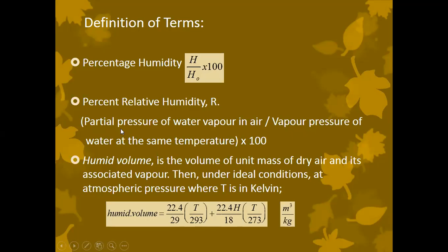These two are very different. Partial pressure is just the pressure caused by one component in a given mixture, in this case the mixture of water vapor and air. But vapor pressure is the pressure that the vapor of a substance is exerting at the particular temperature indicated. And this vapor pressure can be read from property charts in section 2 of your handbook.